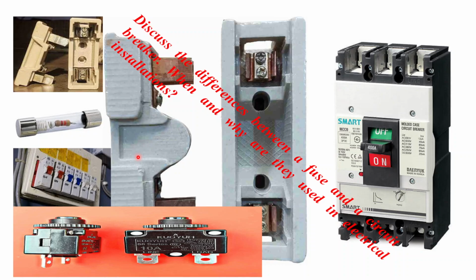When the current exceeds the rated value of the fuse, the wire inside the fuse heats up due to the Joule heating effect until it melts, thereby interrupting the circuit and preventing further current flow. So, what are the characteristics of the fuse? This is the HRC fuse, high rupturing capacity fuse.